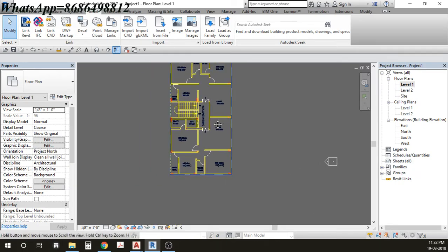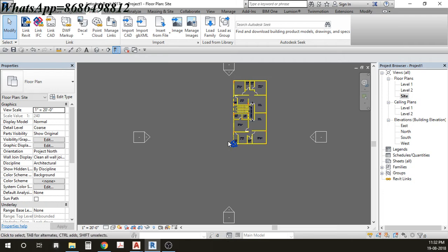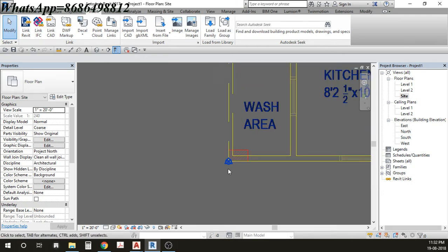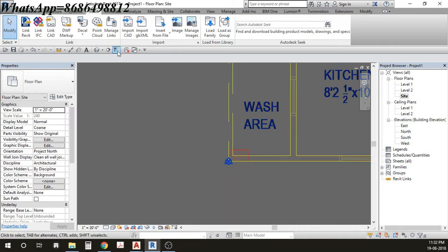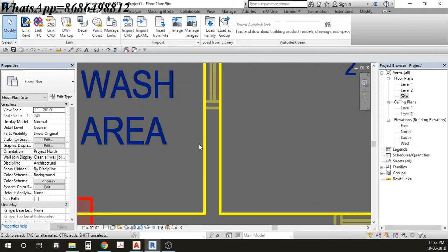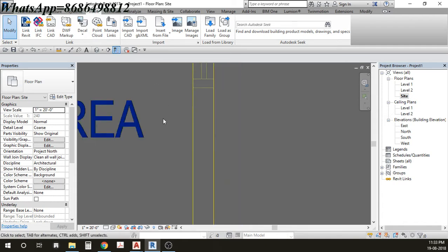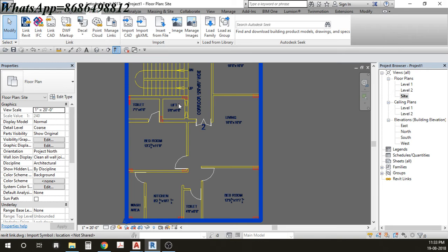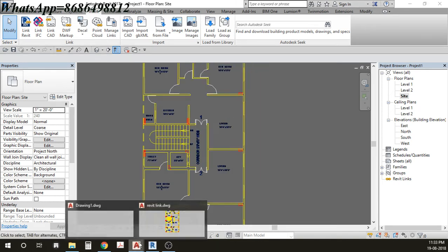So this is how we can actually import the AutoCAD file. Now if I go to a side view, you can see it has come exactly at the origin of the Revit, and there's a big black line appearing. Use the thin lines option. Yeah, it's not going, but basically what thin lines does is make the lines thinner and lighter like this. Okay, no problem.